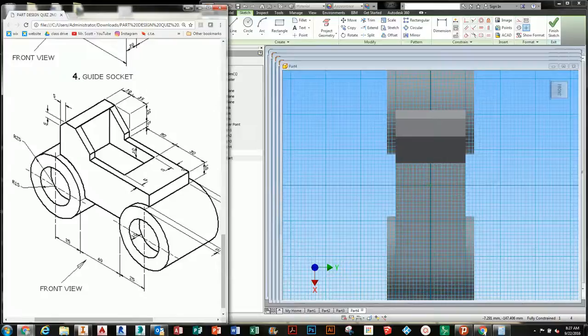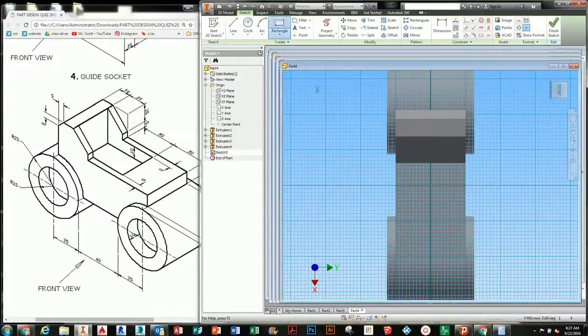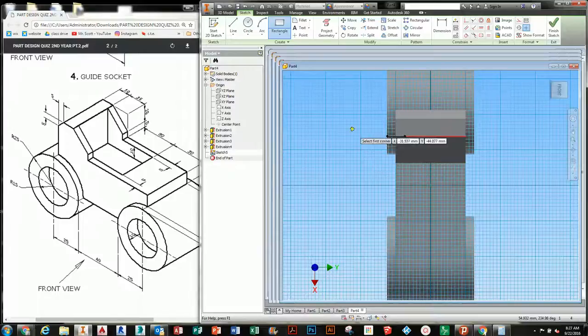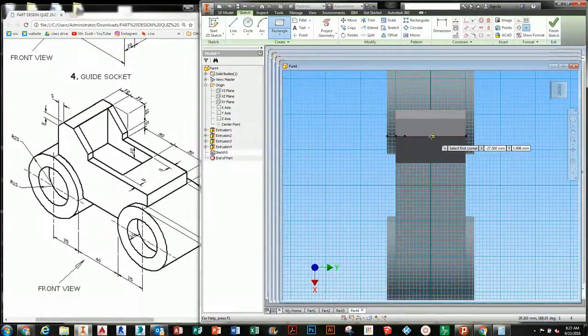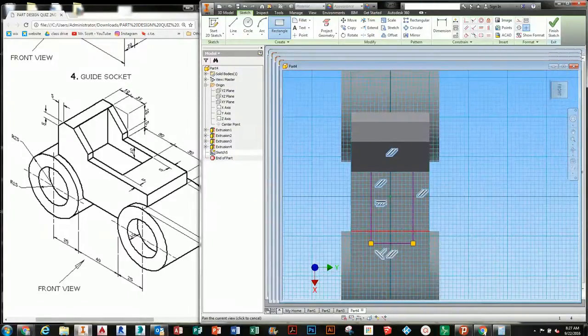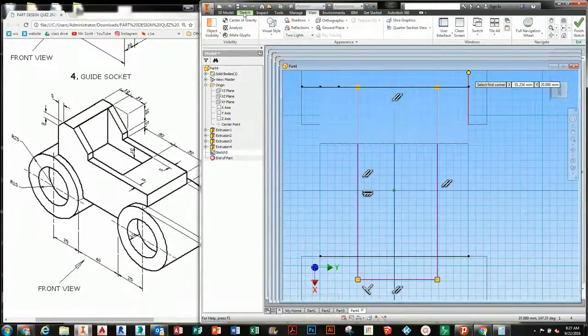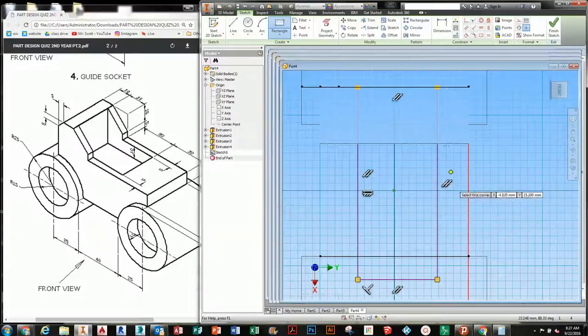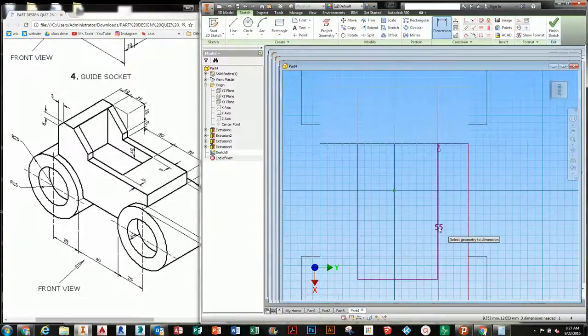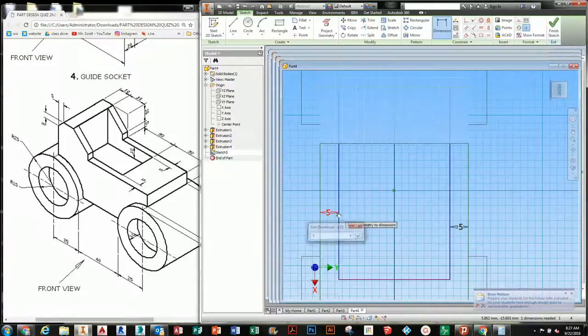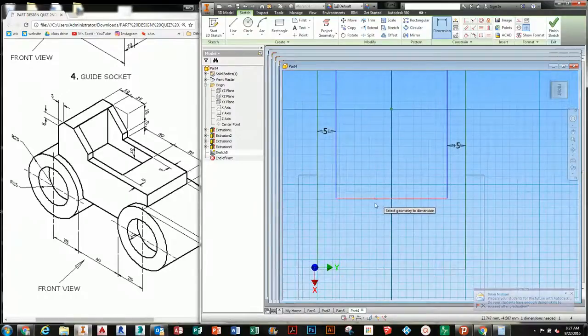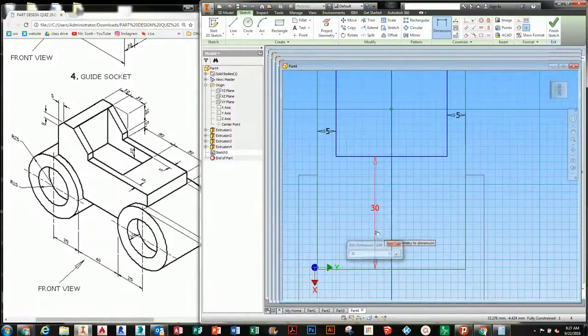And here's how we're going to do that. We're going to sketch just a loose rectangle. If you look, it goes up to the edge of our line here. So this edge of this chamfer, this drawn sketch we have on the back seat, comes out some rectangular shape. So we're just going to loosely sketch and start to define this. You may turn on your wireframe so you can see what you're sketching. And we're going to start dimensioning. This thing is 5 from either edge, and it's 30 from the front edge.